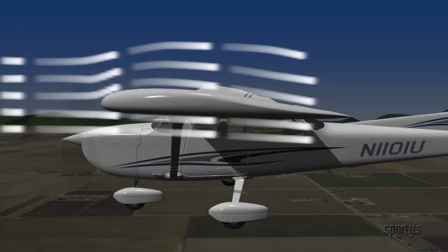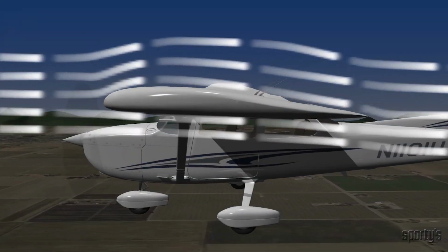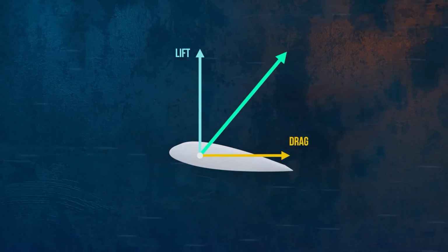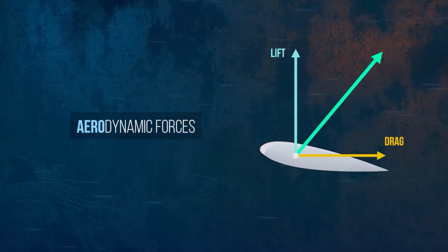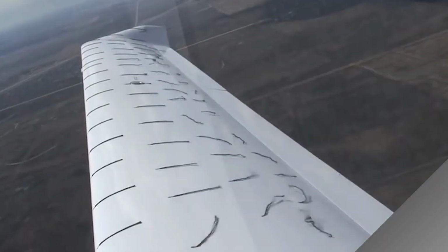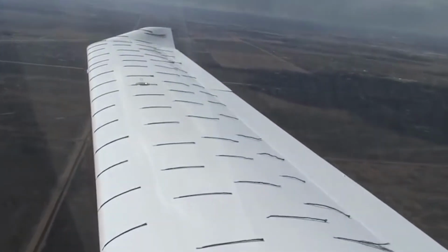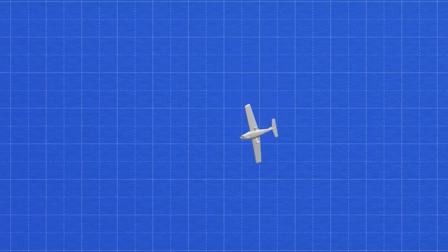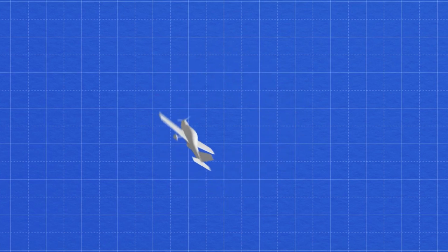What is stall and how is it caused? During a stall, the wings are not able to generate adequate lift, and the plane starts to fall. There are a few common signs of an impending or occurring stall in all planes, such as the aerodynamic buffeting, which means that the plane starts to vibrate. If a stall occurs in only one of the wings, it may lead to another situation called the spin. During a spin, only one of the wings stalls, and it causes the plane to roll due to the difference in the lifting forces on the wings.